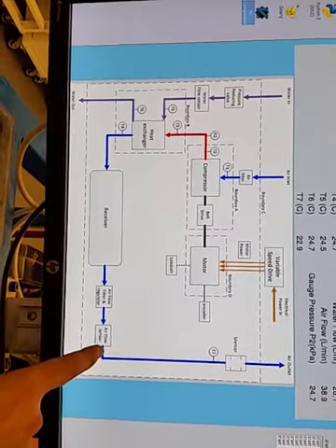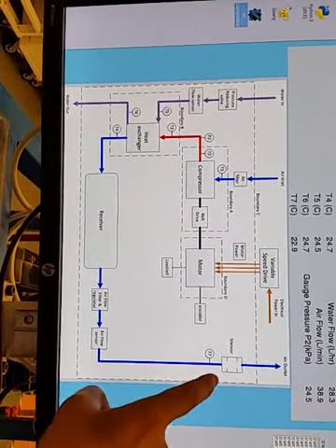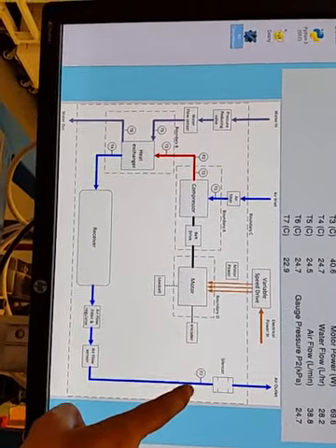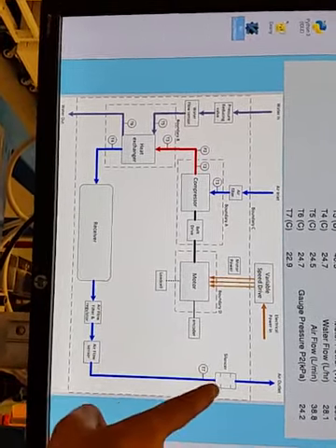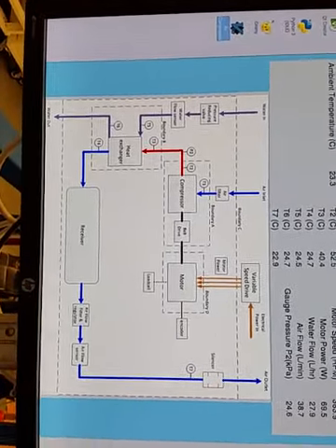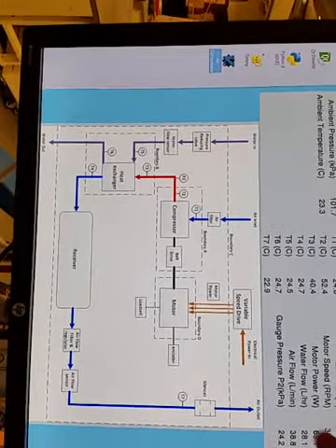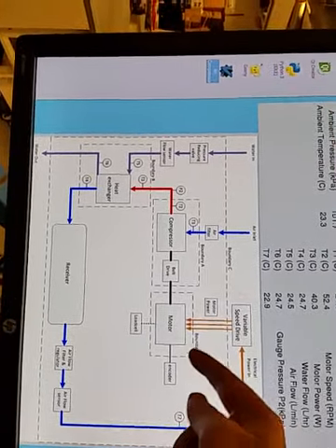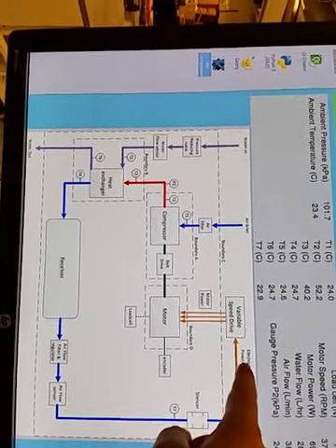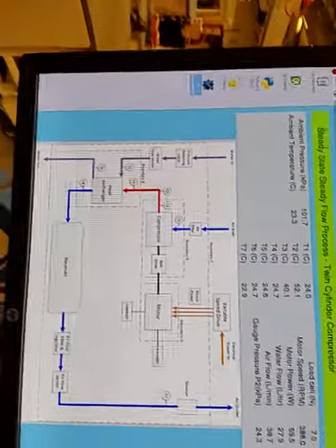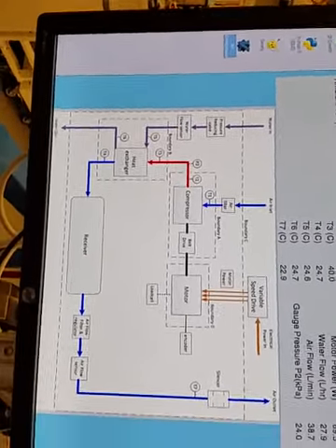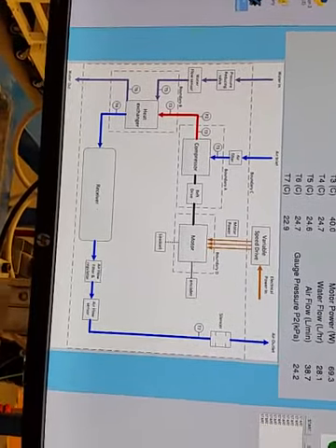and then through the airflow sensor. Point 7, where we have the temperature, is after the receiver, and then the air goes through a silencer and then to the outside. You can notice here as well we have the motor, and the motor drives the compressor. Definitely the motor is driven by electrical power. Why I like this sheet is because it gives us an idea about the whole operation of this air compressor.